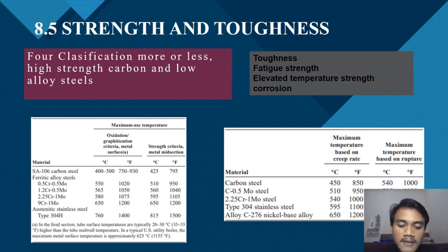during active service. The importance of the subtle change to the fatigue resistance in a component can be illustrated by examining the behavior of a heat-treated alloy steel crankshaft with and without surface treatment by shot peening, which is impacting the surface of the heat-treated part with steel shot or pellets under controlled conditions.